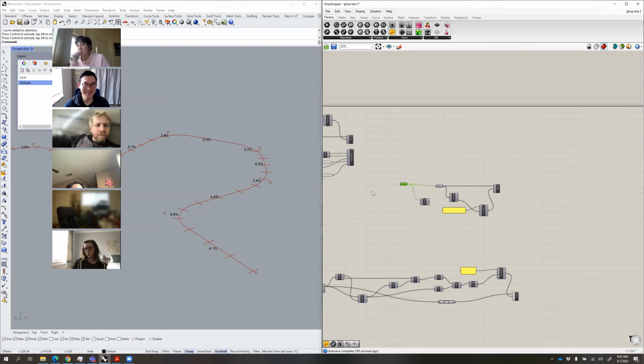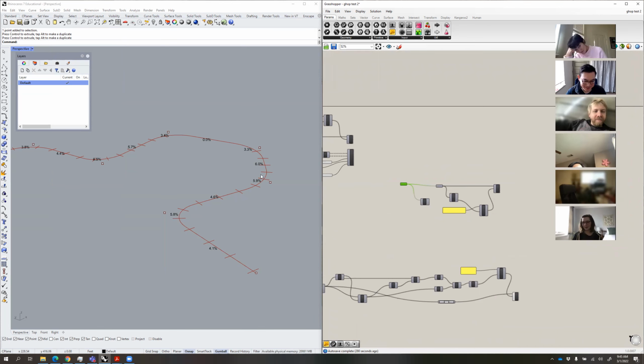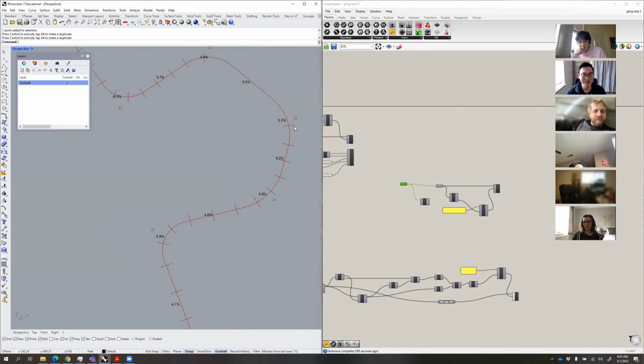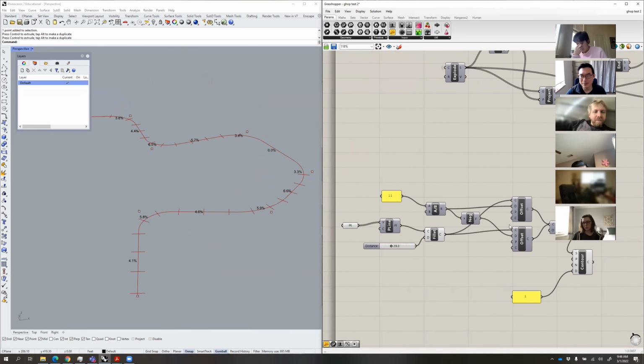All right, sorry. I've been leading you on, and I feel like I wasted like 5 minutes of your time. You need to add a cross slope onto the path. You need to make the water drain off it. Right now there is no cross slope on this. The water is just following the path itself, and that's why I was hoping that the grading knowledge you learned would come into play: every path that you design in almost every design needs a cross slope. Water needs to shed off it. So here's how we do that.